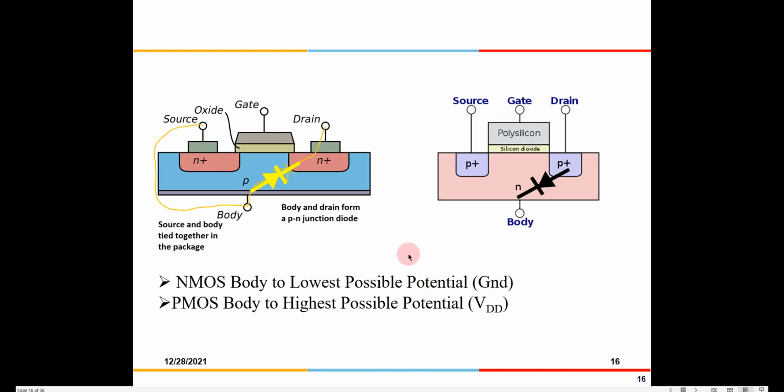Okay. Now another thing which we have to take care in our designs is, like you have an NMOS, whenever you have a body connection also, that is known as the substrate. So this substrate is a P, and this you have N, so you have a diode junction here. You will also have a diode on this side also. So you don't want current to flow from this P to N, forward bias junction.